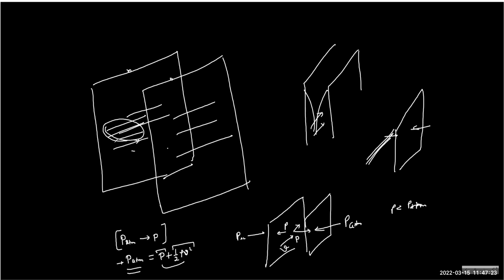And here the airflow will be horizontal, so we can think of a streamline in the horizontal direction. So the third term will never come into the picture, because the third term is all about how you write it from the reference. So only the first two terms will come, but the sum of static and kinetic must be constant. So in the very beginning we had only static, later on we have static and kinetic, and we can equate them, but the wall will be pushed inside or thrown outside depending on the pressure times area.